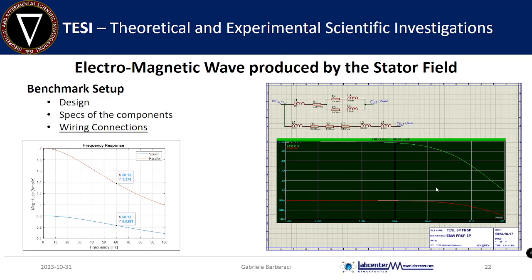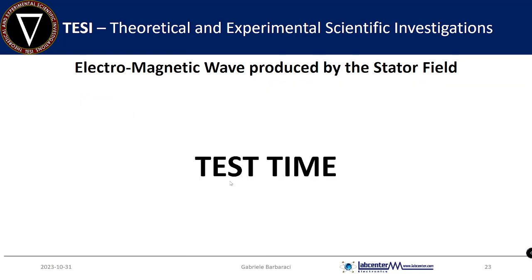We extracted the points and imported them into numerical software to understand the gain difference between the two kinds of connection at a frequency of 60 Hz. We discovered that we have double the current in the parallel configuration, something we had to consider when letting the coil work, to prevent it from warming up excessively.